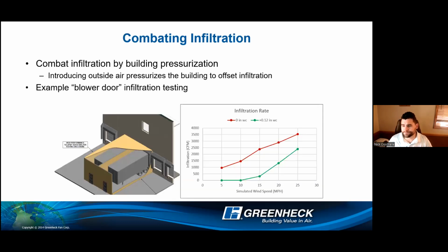Next, combating infiltration by looking at building pressurization. So this is the key detail in our market, especially with our direct gas units for space heating. The big ticket is combating infiltration through pressurization. So what are you doing? You're bringing in that CFM, you're pressurizing the space, you are pushing against that infiltration, that cold air. You have multiple dock doors open. If you're bringing in that makeup air, you are creating that entire bubble of the space to push that out. It's that heat air curtain kind of dropping down and preventing that cold air from coming through those either open doors or other infiltrated areas.